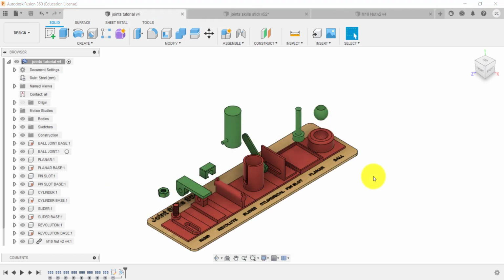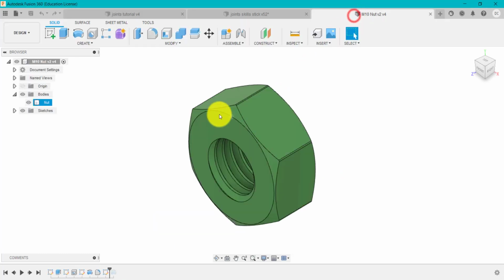The first thing that we need to understand to create an assembly in Fusion is that we need to create components. When you're creating designs and creating extrudes and any different features, sometimes it will give you the option of adding, cutting and so on, and in that option you will find that you can create a component. But sometimes if you ignore that and you get to this point here, we do not have any components, so this is not a component.